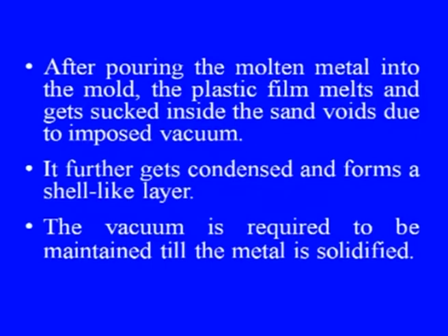The vacuum is required to be maintained till the metal is solidified. Then it is released, allowing the sand to drop away, thereby leaving behind the casting with a smooth surface. The process does not require shaking out equipment to remove the casting, and the sand can be reused after cooling without any treatment.